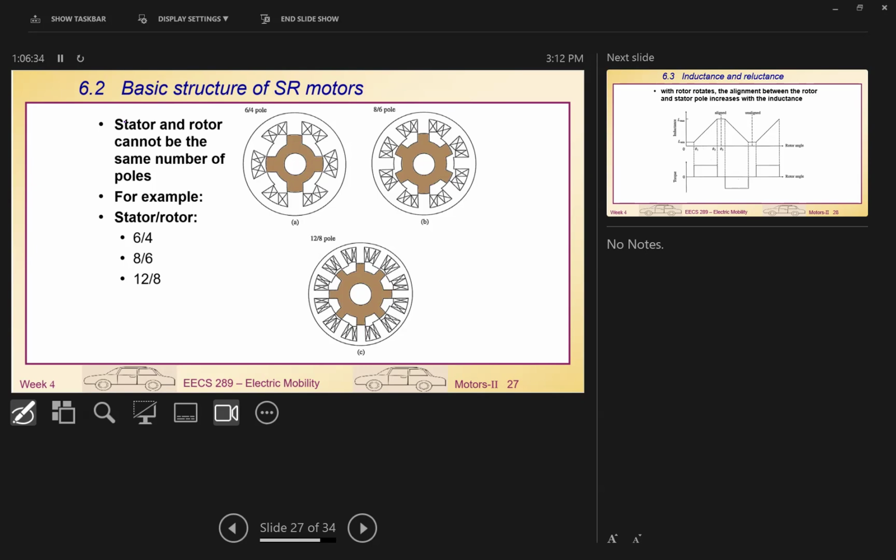When we energize them, the magnetic flux will go through the path of lowest reluctance. So it automatically searches for that particular path, like in here. If they are not in that position, they will try to rotate until a certain alignment is reached and the magnetic flux can go through. The motor rotates the rotor by natural principle to allow the flux to go through, so that rotation can be established.